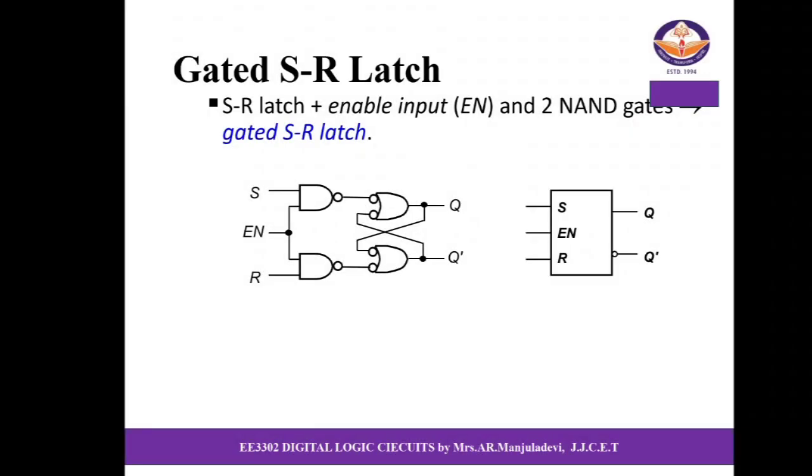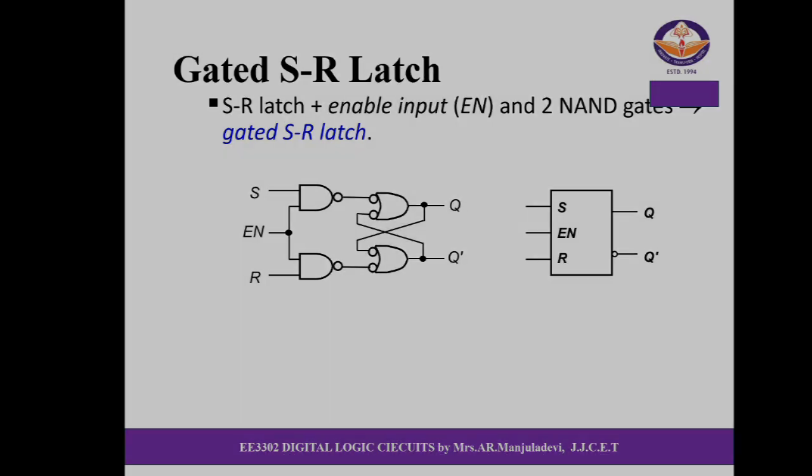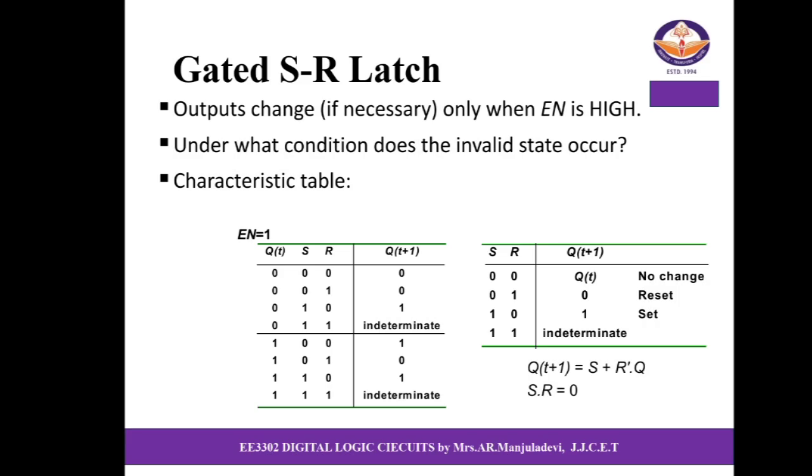Gated SR latch. It is the combination of SR latch and enable inputs with two NAND gates. This is the logic diagram of the gated SR latch. The output changes only when enable is high. This is the characteristics table of the gated SR latch.